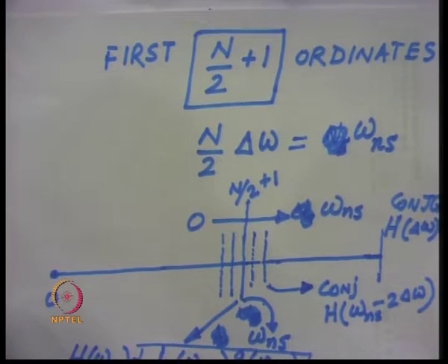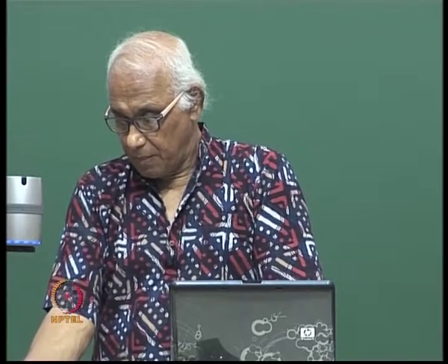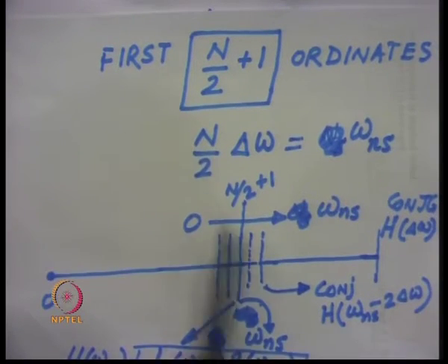Here the period is taken to be the entire duration of the excitation plus delta t, after which the repetition takes place. In other words, if T is the duration of excitation, then T plus delta t becomes the period, and that also is equal to n into delta t.